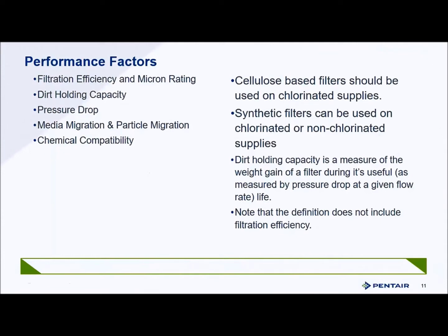If we don't have good pressure, we're going to see a greater pressure drop across that filter over time as it loads dirt. Media migration and particle retention: one of the things we don't think about in filtration is that as water pulses through, you get a relaxation and a force placed back on that filter cartridge.